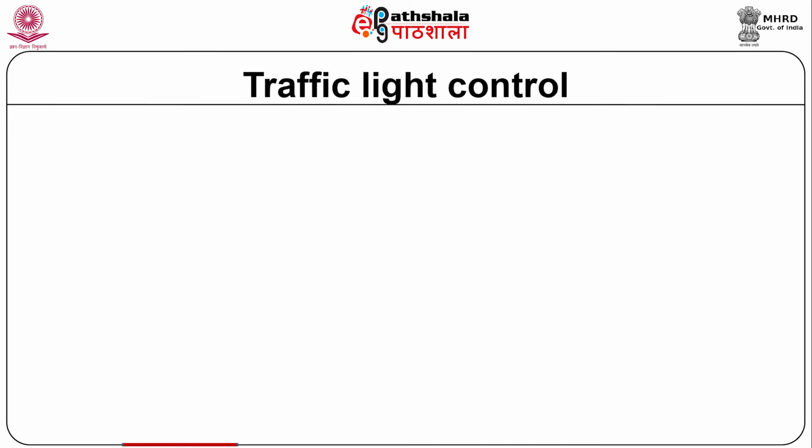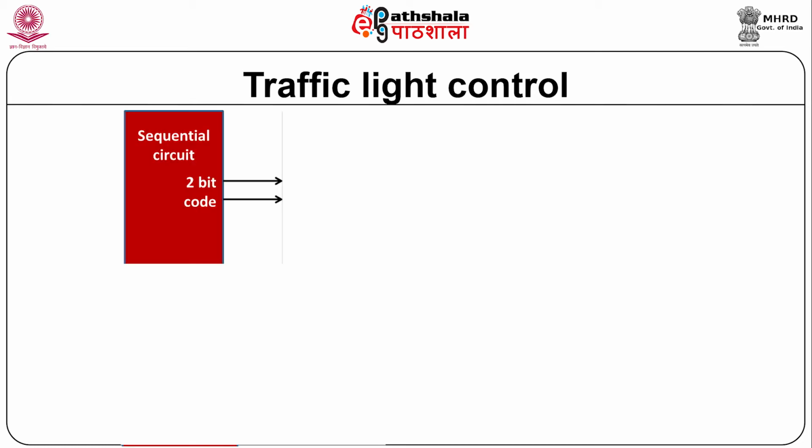Based on the state diagram, let us construct the block diagram for the traffic light control system. There are 5 simple blocks consisting of combinational and sequential circuits. The first block in the traffic light controller is a sequential circuit. This sequential circuit requires a 2-bit state machine to implement 4 states.